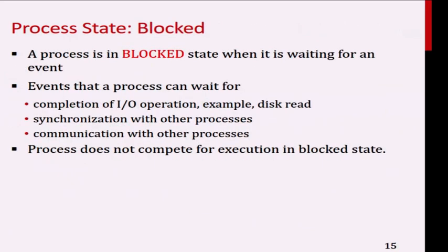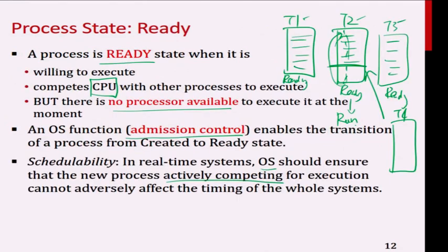The important thing you must remember here is this: if task 4 comes in and task 4 is higher priority, so if I say this is 1, 2, 3, 4 priority, and task 4 is now running, what is the state of task 2? Because task 2 is preempted, task 2's state is now ready. So from run, we go back to ready.